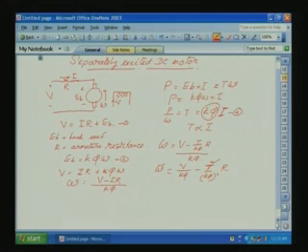Now, we found that torque is proportional to I, and omega also depends on the I here. We have the maximum speed when T is equal to 0 or I is equal to 0. I is equal to 0 means there is no load. Okay. So, this is the omega 0. The maximum speed for a particular V is omega maximum, which is equal to V by K phi.